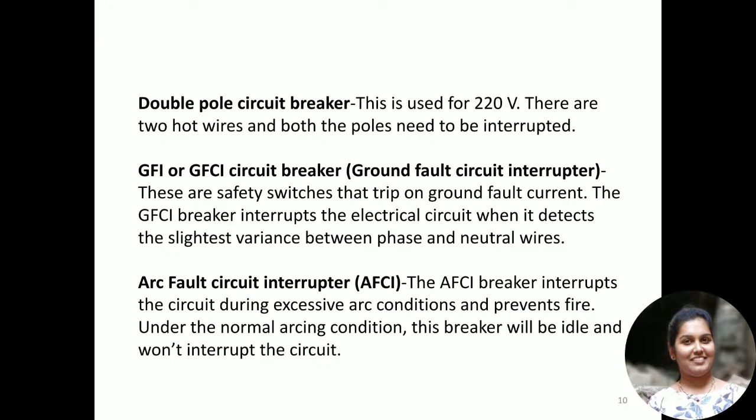And the last category of circuit breaker is arc fault circuit interrupter, AFCI. The AFCI circuit breaker interrupts the circuit during excessive arc conditions and it prevents fire. Under normal arcing conditions, this breaker will be idle and it will not interrupt the circuit.